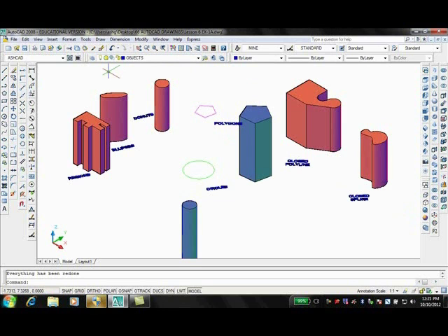In order to make an extrusion with a positive taper, I drew a magenta colored polygon in the middle at the top of the screen, and I'll type 1 to specify an extrusion height of 1 unit and 10 to specify a taper angle of 10 degrees. In this case, you can notice that the taper on the object is clearly visible.